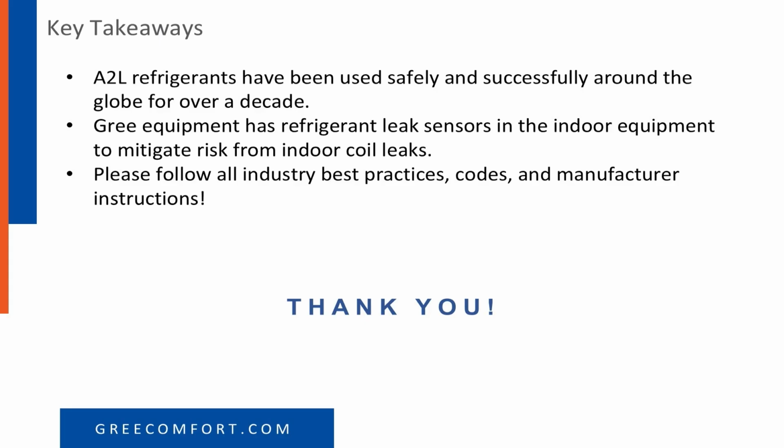Okay, very, very safe product if you install it properly. But that goes with any product that you install, all right? Gree Equipment has refrigerant leak sensors in the indoor units to mitigate risk from indoor coil leaks. And like I said, they trip at 10% concentration. Lower flammability limit of R32 is 12. So we're never going to let it get rich enough to burn.